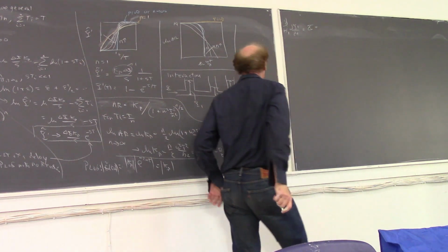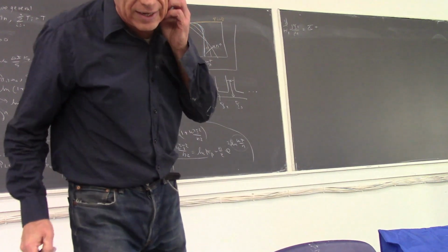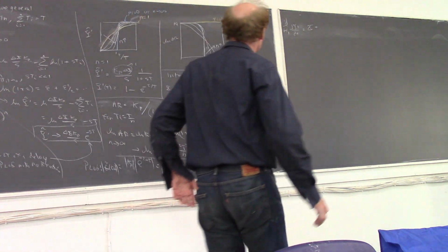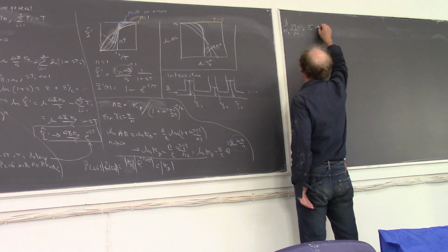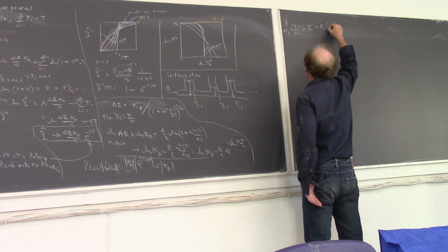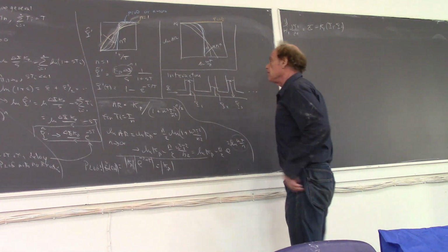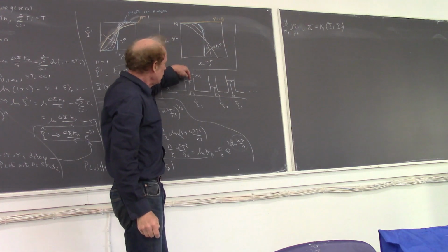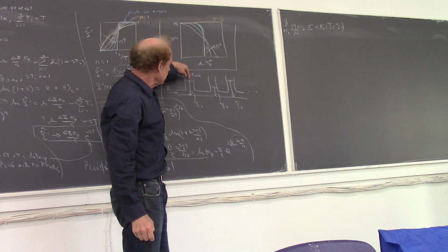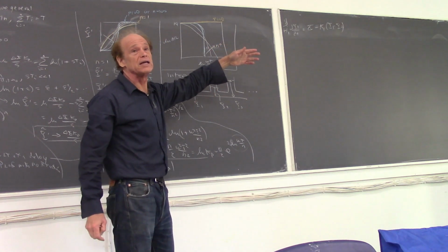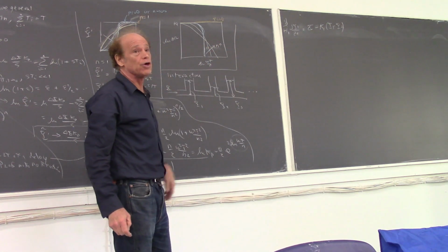And then I also have, I can write this with a plus or a minus, let's write it with a minus. So k1 times (y1 minus y2). So if this is higher than y2, then the hydrostatics is going to push stuff from here to here. Now, of course, if this is higher, then y1 minus y2 will be negative, and it'll go the other way.